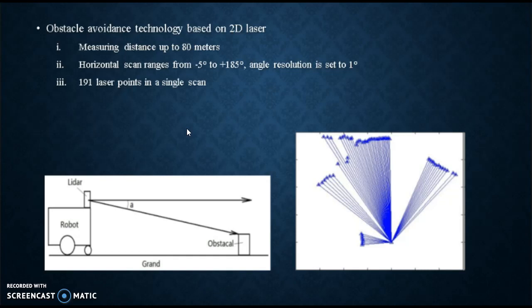The traditional artificial potential field method has some problems, such as local optimal solutions and the target being inaccessible when the robot is near the target. There are some improved artificial potential field methods combined with fuzzy rules, genetic algorithms, and regression search methods, respectively.